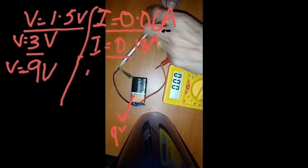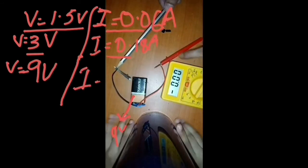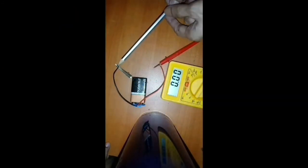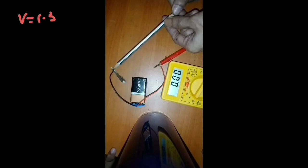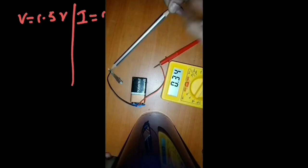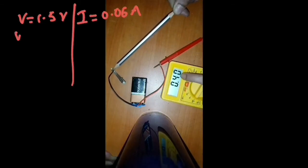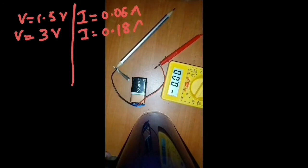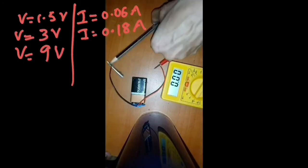Here also I have to connect the positive terminal of the multimeter to the positive of the battery. Then the negative terminal, the black terminal, should be connected to one end of the pencil lead, and now take the reading. So you can see that the current is in the range of 0.35, or almost equal to 0.4 ampere.